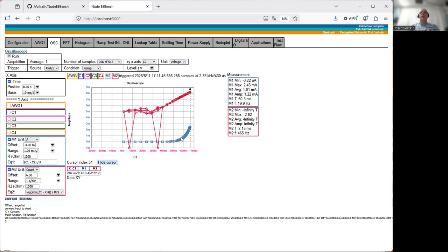So it's a typical diode characteristic where at a certain voltage a current starts to flow. What you see here in the linear axis looks quite different in the logarithmic scale. So math 2 has a logarithmic scale. So there I can see my equation from the diode, which says, okay, I have an exponential function.